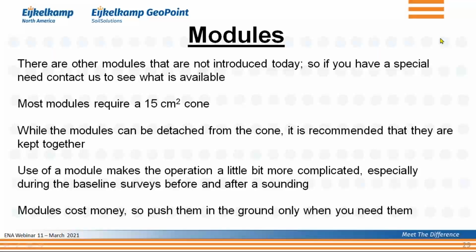The other thing, and that's the one that I mentioned in the last line, something that's fairly obvious, of course, modules cost money. Nobody will be surprised about that. But my recommendation is only push those modules in the ground when you need them. Even if you're very experienced, even if you're very careful, you are going to lose a cone every so often when you push the CPT cone.